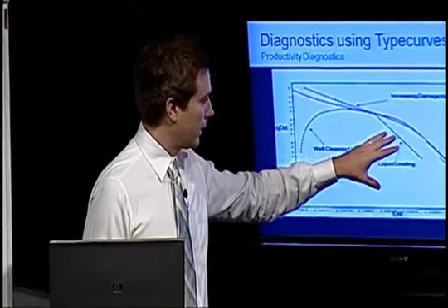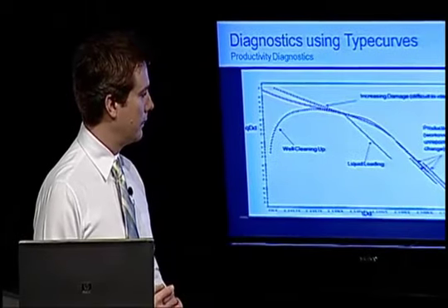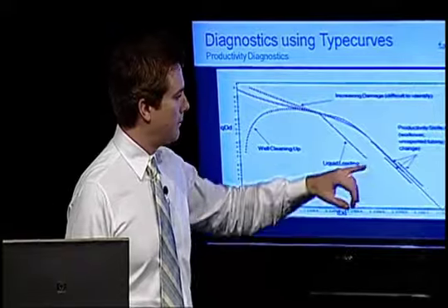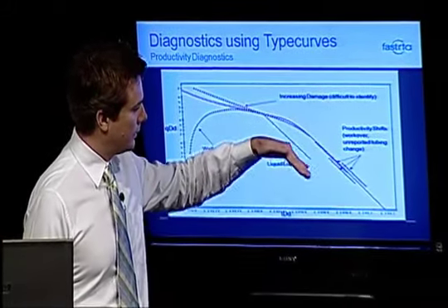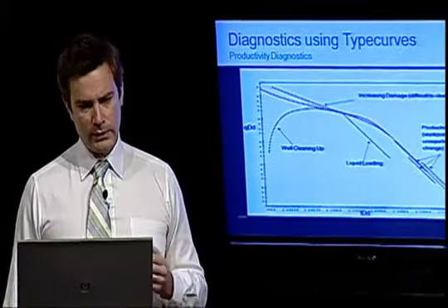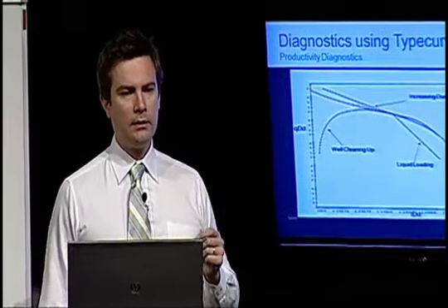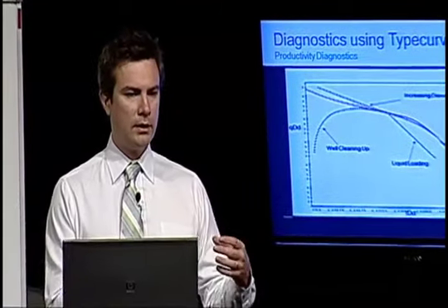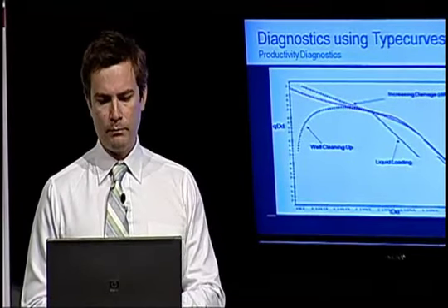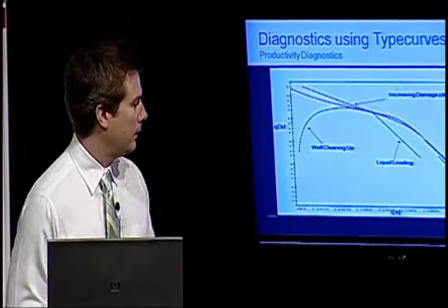So this one we can usually identify if we have enough information and we know the wellbore tubulars, and we understand what's going on there. Some other things that are commonly seen is if you get parallel trends in the data. We see that quite a lot. That could mean that at some point in time, something's happened. So the operator has gone in and done a workover or changed out the tubing. There's some shift in productivity, step change in productivity because of something that happened.